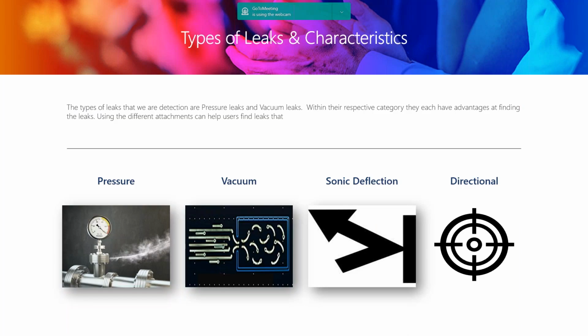All right. So the two different types of leaks, I know I've touched on them a little bit here, but obviously pressure leaks, leaks that we typically say are 5 psi and above. Our equipment is a no-brainer at utilizing ultrasound when finding those. And then vacuum leaks, obviously, it's just the reverse. It's the air leaking into a vessel or a pipe or whatnot.